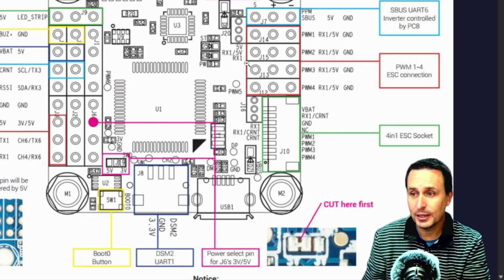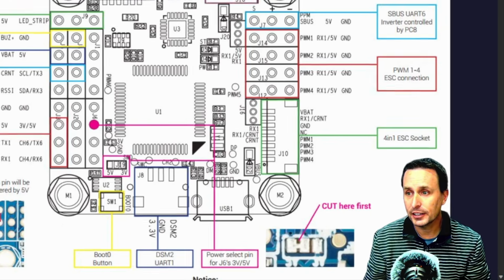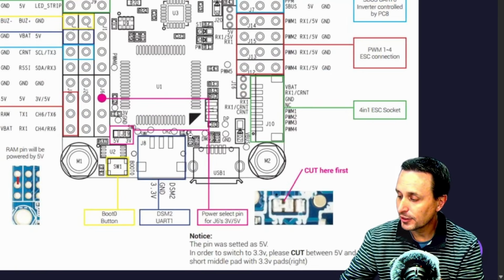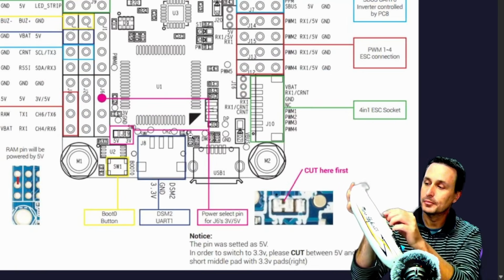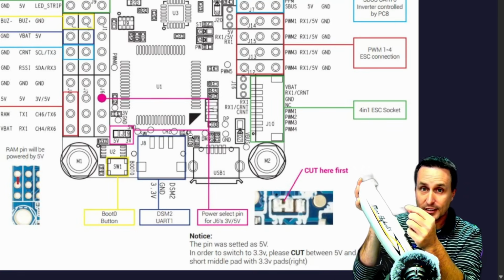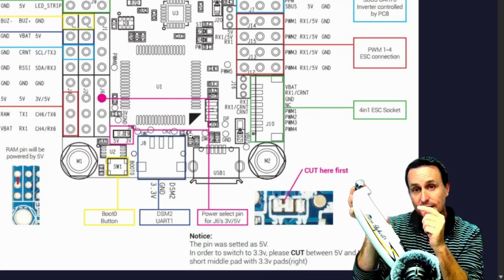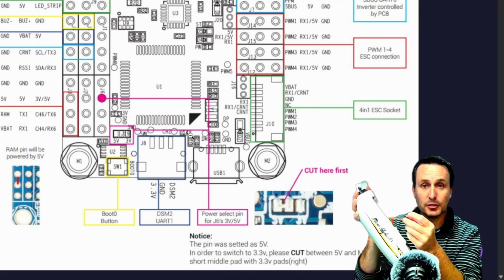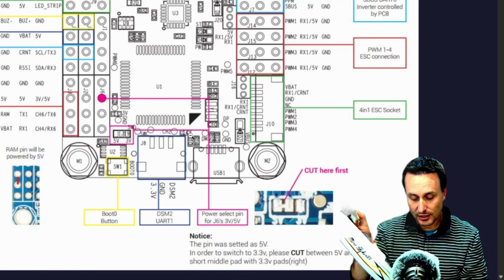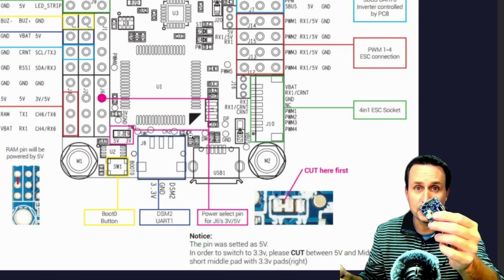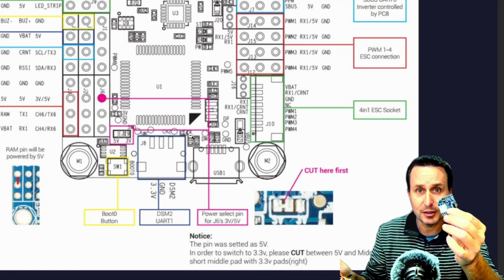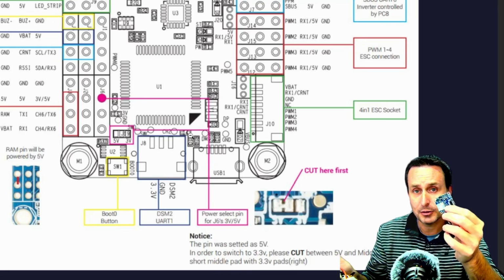And what's also great about that is that when I go ahead and plug in, I need to power this. I'm going to end up powering it with the BEC on the wing here. The ESC is going to have a BEC that puts out 5 volts, and that BEC is going to be rated typically on a wing or a plug and play to operate the servos that come with it. Otherwise, if you're going to put all your main power through here and rely on the BEC that comes on the flight controller, you've got to be cautious about how big that BEC is and how big your servos are and how much power they draw.